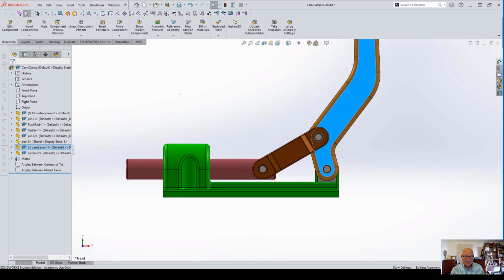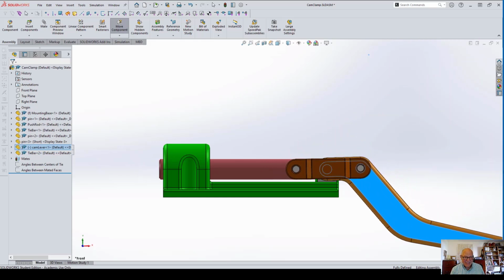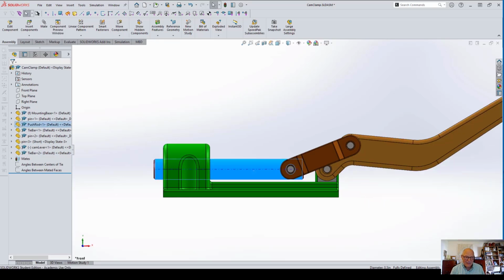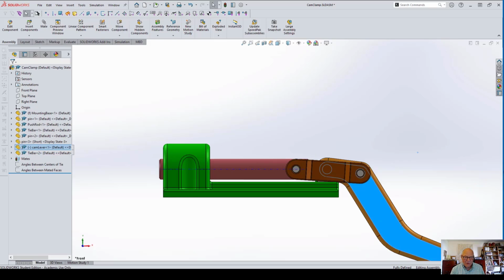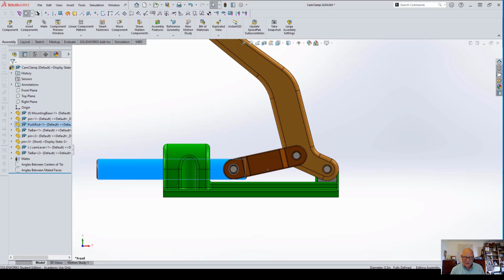So you can put tension on this as well. In other words, this clamp is bolted down to a table. The thing we're dealing with is also either bolted down or put in between this and a stop. Now, in the opposite direction, this gets to this point right here. It's not going to stay there, because if it got any tension on it, it would just open up like that. But if you go all the way down till it hits the base, now attempting to pull it in that direction tries to pull it through the base, and again, it can't do that. You push it back to a point. Then, when you pull it, it might go down, it might go up. If it's any amount at all above horizontal, pulling it opens it up like that.